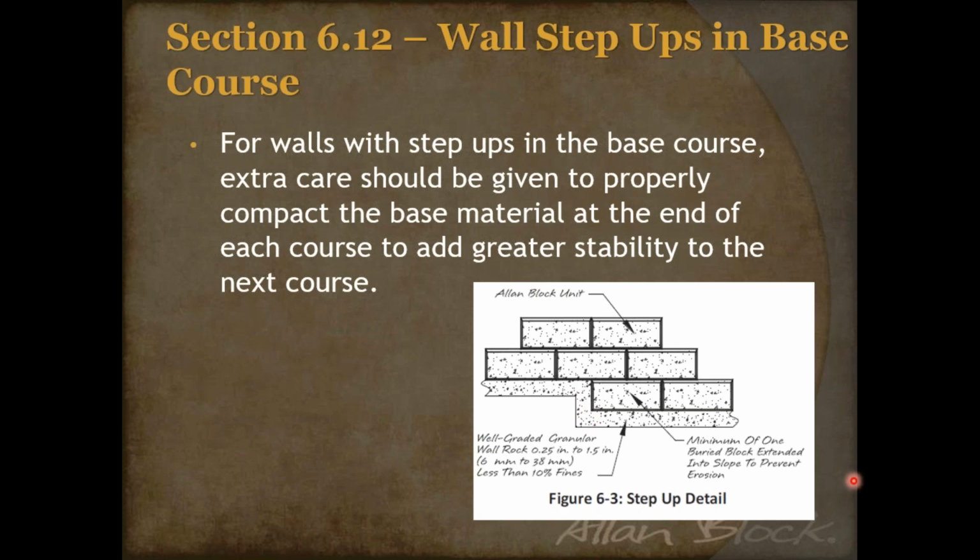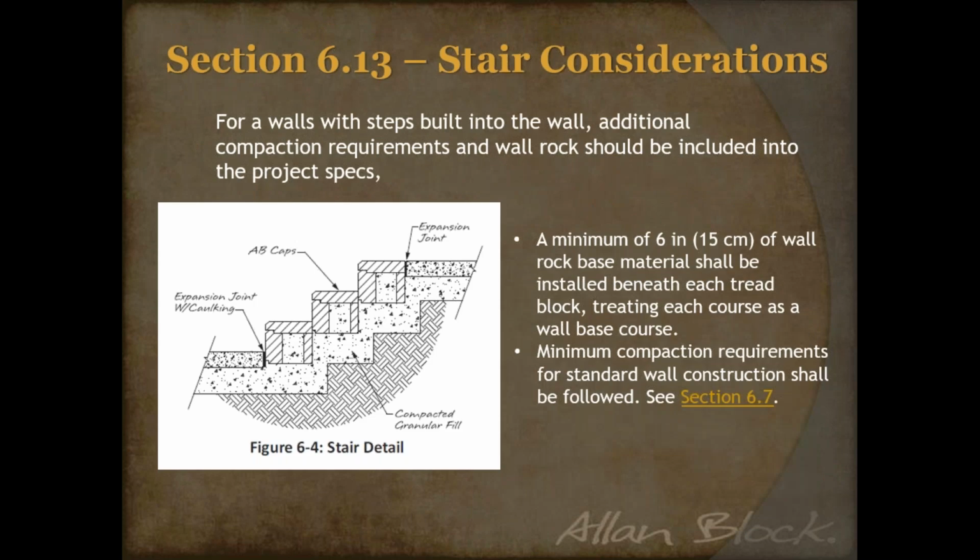Right. And then one of the last ones here is similar to what we just talked about with stairs. In fact, constructing stairs is a hot topic. We did an ABU online for contractors a couple months ago, and it was probably one of our best-attended sessions, where we talked about stair construction. Unfortunately, the conclusion is there's no silver bullet. Every set of steps is a little bit different, depending on the tread depth they want to do, the rise. But what I tell the guys when you talk about compaction is, don't get cute. It's easy to show this line art with 90-degree bends, but really we want to oversize the excavated amount.